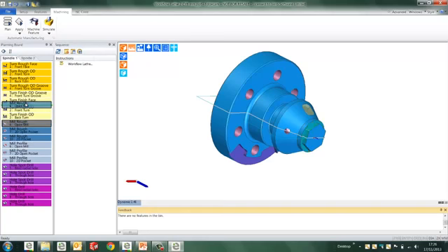But first of all we'll see here I'm going to drag the rough mill up the tree, and I can influence the manufacturing order by doing this. Now as I said before, we do build elements of safety into this technology, and here you'll see if I start to move the hole drilling about, it's not allowing me to drill the holes before I've spotted them. That's an illegal move. So there are certain elements of, as I say, safety built into this.